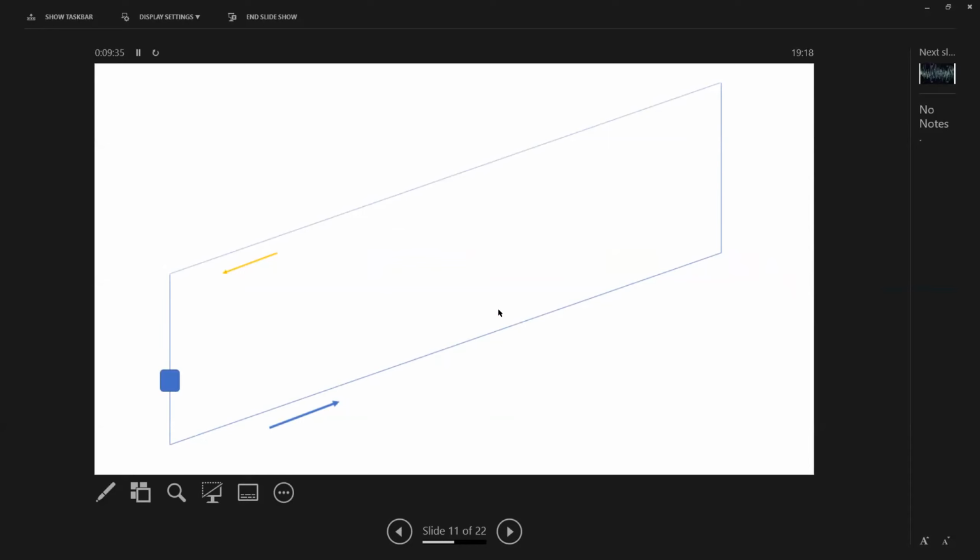Instead of following the instructions that the company, at the time it was called Kenway Robotics, gave, instead of laying a ground or a directional line on the floor and then cutting lines in the floor to allow the return line to come back and crisscross and cancel out, the Disney engineers said, let's simply put that line that goes on the floor to the end of the hall, and then we'll run it up the end, and then we'll run it across the ceiling, and we'll run it right back down. Yeah, simple, right? A lot easier than all that crisscrossing wire on the ground.